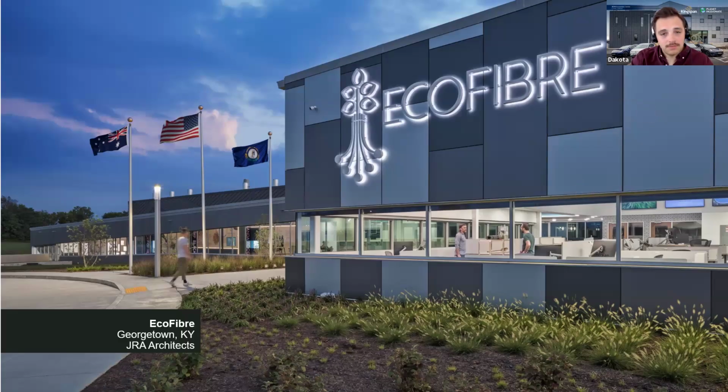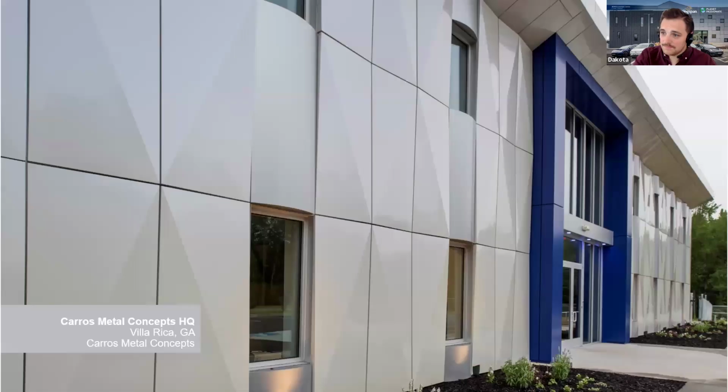So if we are doing a really complex geometry, if we have skyward facing panels, IMPs are going to need that backup wall. Not an entire backup wall, some additional sheathing, some dense glass or something like that, in order to make sure that the wall is going to again perform as intended. So that's our one drawback, of course, is that if we're getting too crazy, we do have to add an additional sheet of layer. That's the sacrifice we have to make for good design. But again, you're still going to get that install speed that you're looking for, because then we're only 2 trips around the building. So there you go. But you still can achieve some great looking facades.